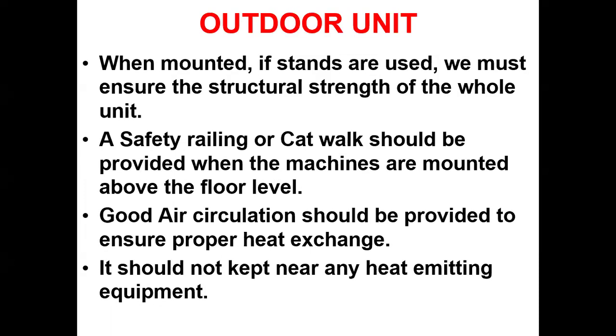Later, it's about the outdoor unit. While mounting an outdoor unit, proper airflow should be maintained, and you shouldn't place your ODU near any heat emitting equipment. At the same time, a safety railing or catwalk should be provided when the machines are mounted above the floor level. That means normally on terrace sites, if you are implementing these outdoor units or ODUs, you must use some kind of safety railing for the maintenance guys.